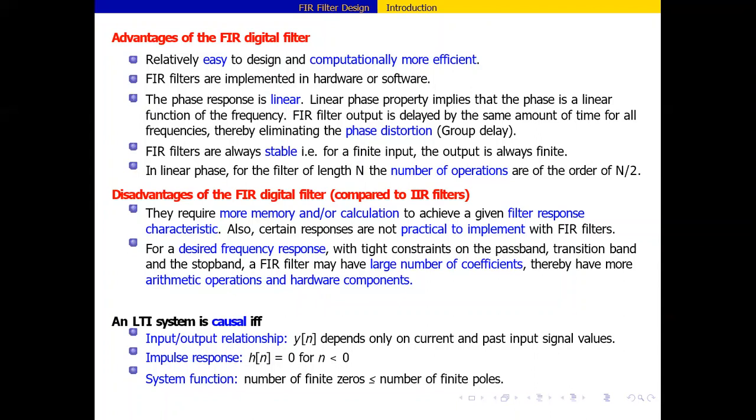because it is having only the forward path diagram. That means there is no feedback. It is simply like an open loop system. So we already know open loop system design is very easy compared to the closed loop system. So here FIR filter is like an open loop system, and there is no feedback here. Whereas in IIR there will be feedback. Wherever the feedback is there, that type of filter is called the recursive filter. So FIR filter is a non-recursive filter, IIR is a recursive filter.